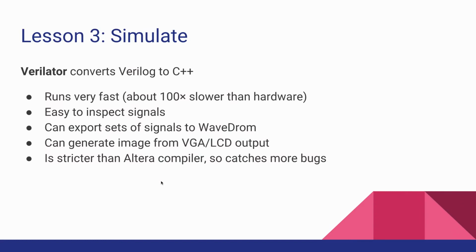Right, one more thing about Verilog is there's a Verilog spec. The history of Verilog is that they did it first for humans to consume, and then they wrote simulators to simulate the hardware, and only later did they actually use it to synthesize hardware. So when they were in the simulation phase, they wrote all this spec about what simulating Verilog means, and it's a very specific spec. Unfortunately, it doesn't match what happens later with synthesis. So it's very easy when you're writing Verilog to get what's called a mismatch between synthesis and simulation.